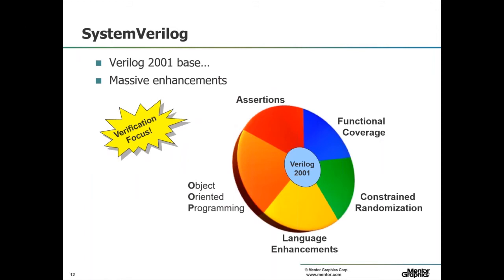But dropping back over there, that first generation of verification languages is what really had the IEEE say, hey, this is good stuff. We need to have a standard for this, just like we have a standard for hardware description languages, VHDL and Verilog. They came up with the SystemVerilog standard, which took the Verilog language and added some enhancements to Verilog just for RTL design.